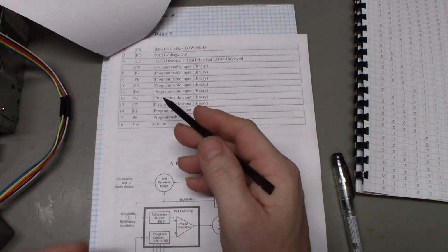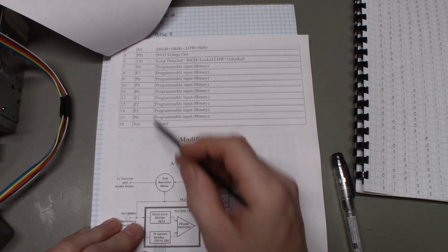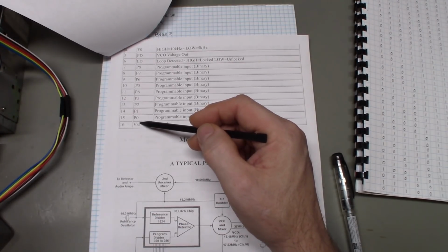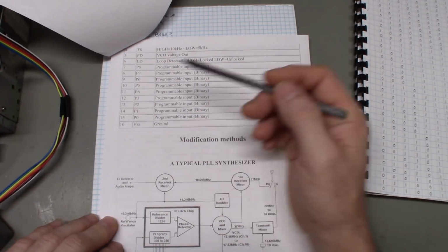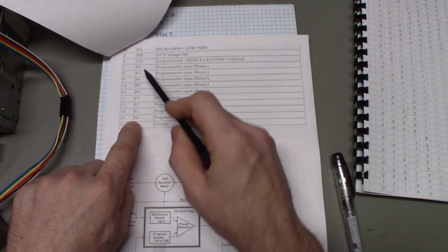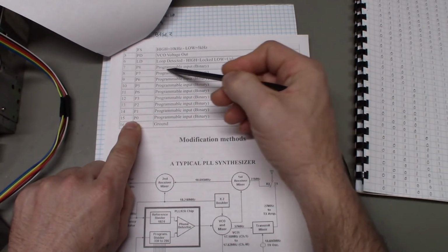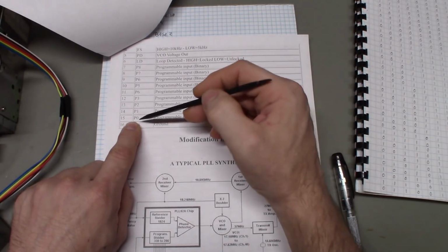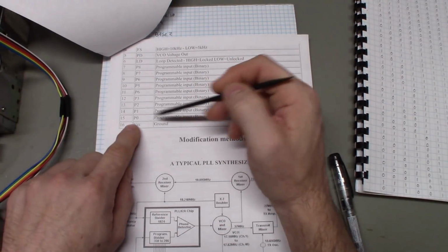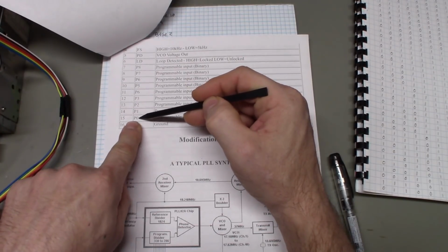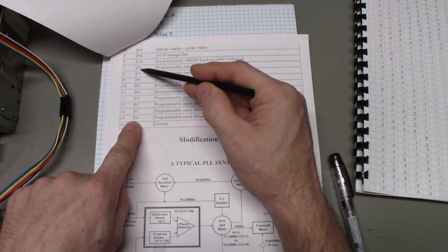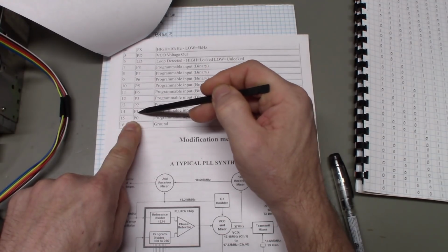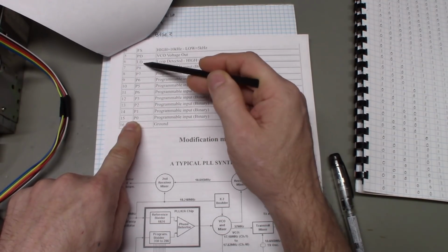Now there's what I call the pin identifier. That's usually a 2 or 3 letter code or number, or letter and number code. You can see it's P0 to P8 for those programmable input binary pins, okay? So I call those the program pins. That's P for program, or programmable, but it's programmable pin 0 to programmable pin 8. So that's a total of 9 pins, because 0 and then 8 more pins.